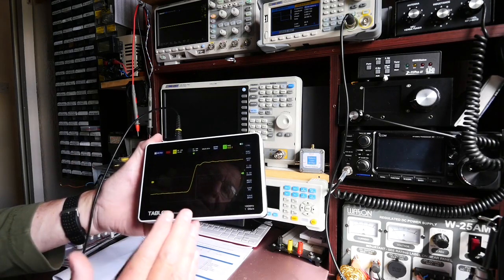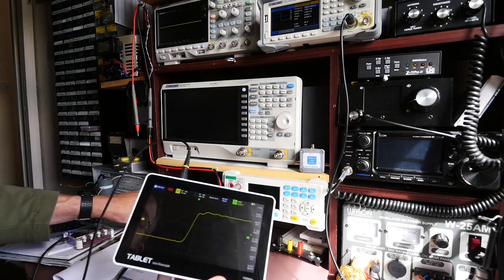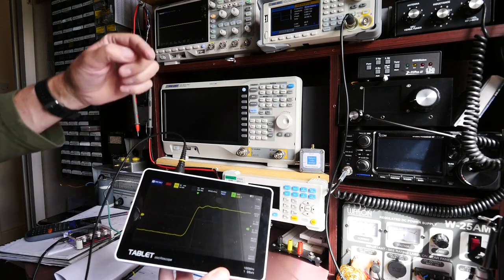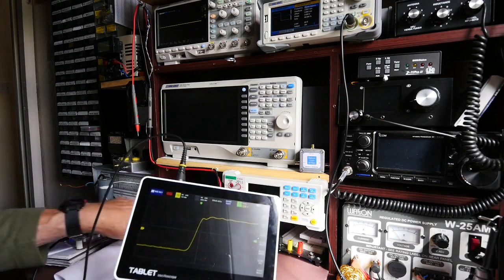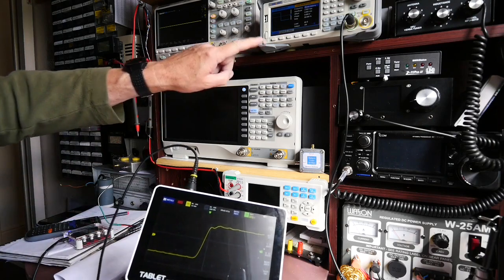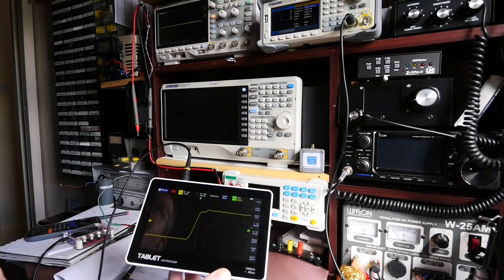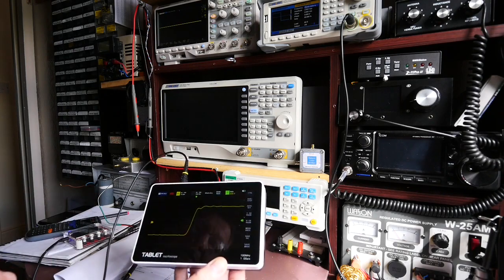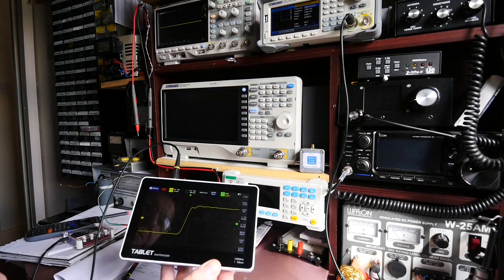So we'll see what that does to the maths, but we know that the rise time of the Schmitt trigger oscillator compared to the signal generator is significantly different. Alan Walk estimates 2 nanoseconds for that, whereas the signal generator spec here is telling me 3.8 nanoseconds. So let's now hop across to the calculations in the table and see how all this works.